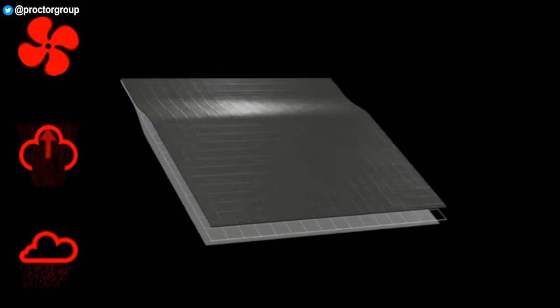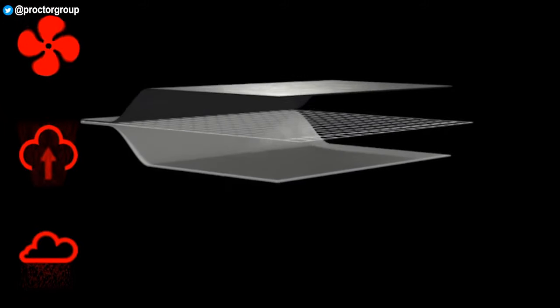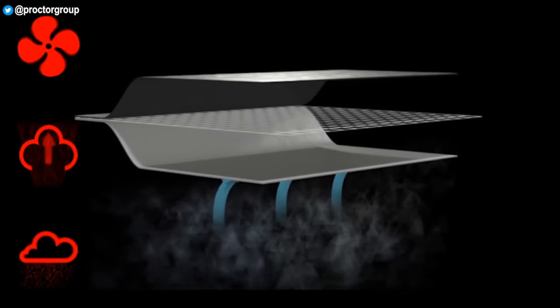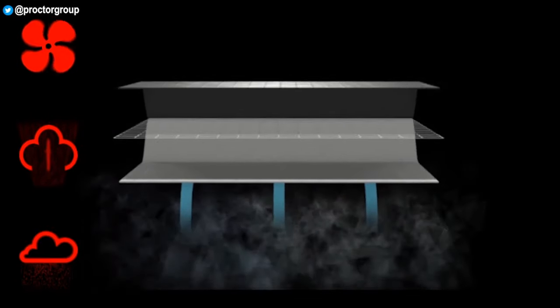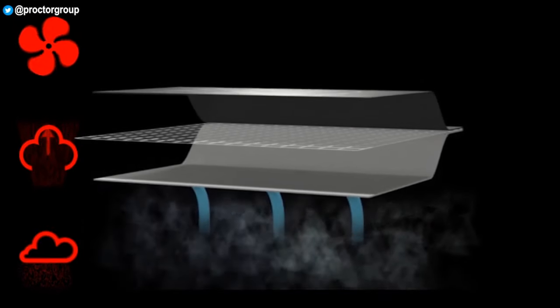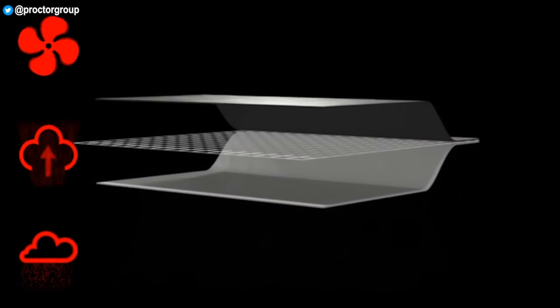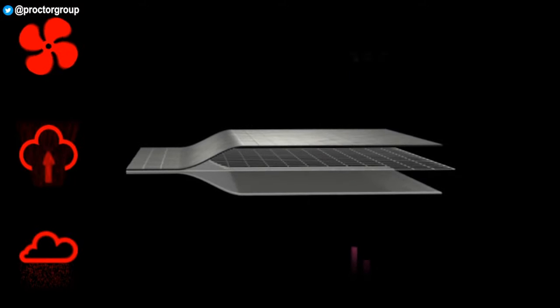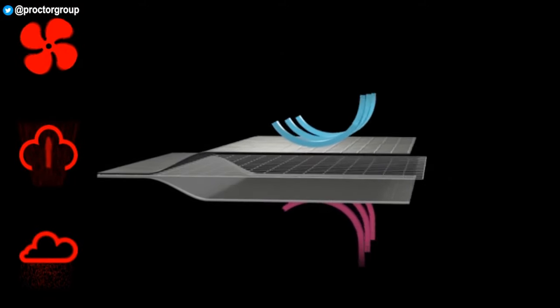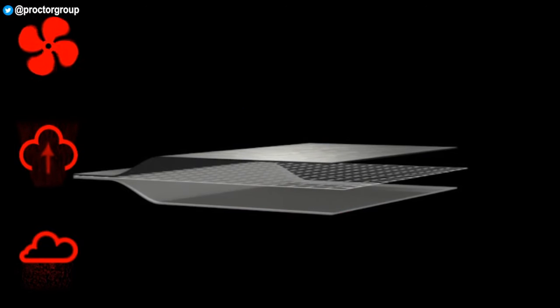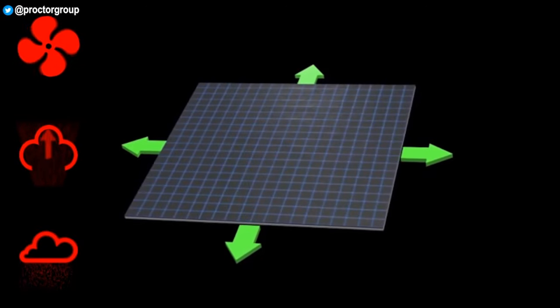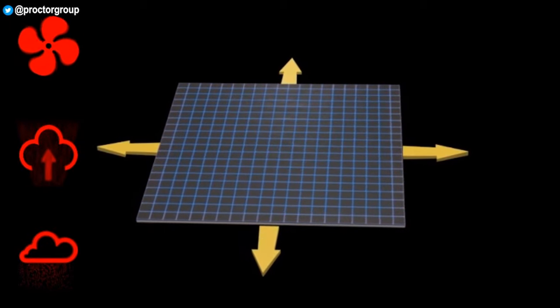Vapour control layers. In comparison to breather membranes, vapour control layers are relatively simple. Most vapour control layers are polyethylene and/or aluminium, with no perforations to ensure vapour resistance and airtightness are maximised. Some vapour control layers add a layer of reinforcement to prevent tearing, and these reinforced membranes are generally preferable as the performance of the membrane is only as good as its continuity. Unreinforced membrane can tear and stretch unless care is taken during installation.